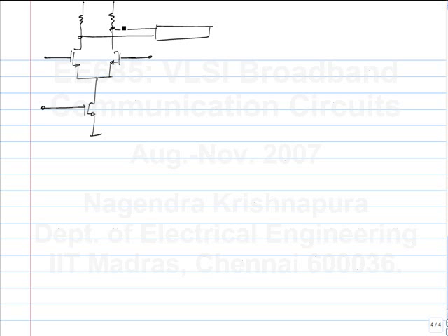And equalization essentially here is high pass filtering, right? Because the channels are low pass, you have to realize a high pass filter. What are some ways that I could do that? Oh, no, we can't play around with the transmission line, because that's a channel that you have to plug into. So let's say this is the boundary of the chip, and whatever you have to do should be inside here. It can also be inside the receiver chip, but let's now stick to the transmitter side.